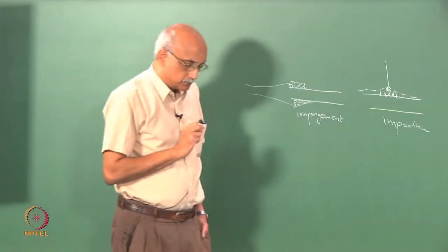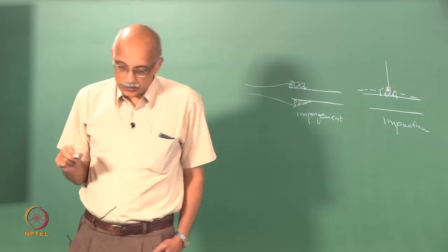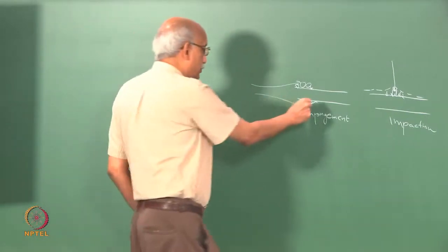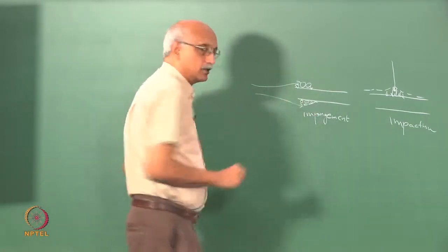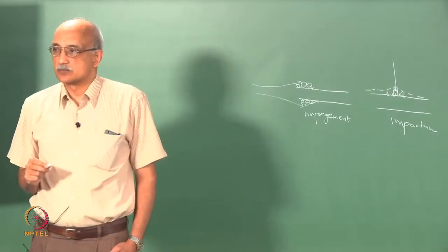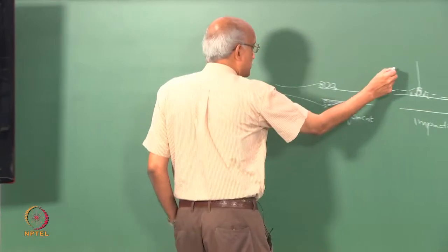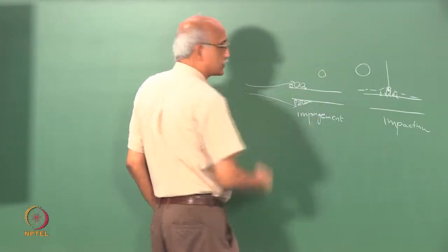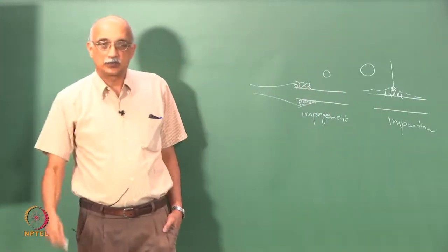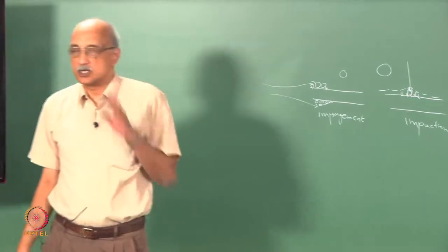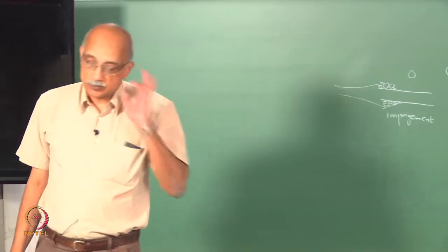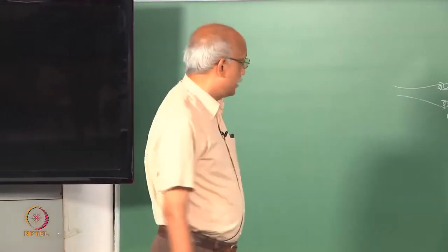Here the particles do have sufficient inertia that they will separate from the flow, but they will only do it close to the surface on which you are trying to collect, right. So, these particles of this size are just not large enough to be effectively captured by inertia, but they are large enough to be collected by impingement forces.